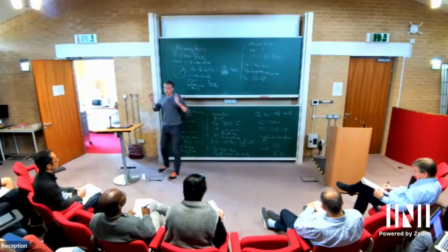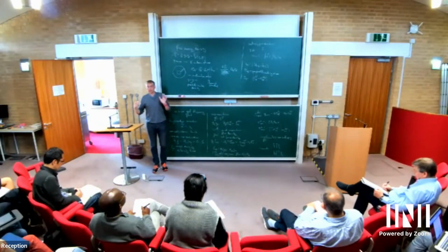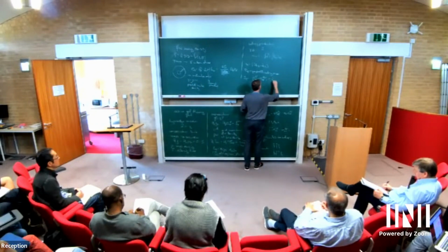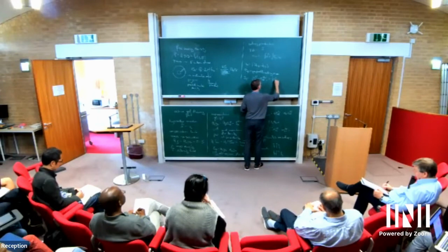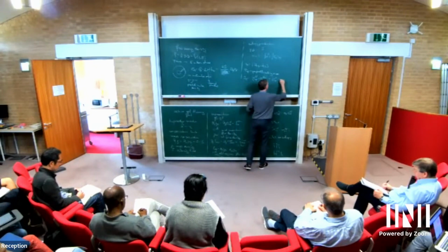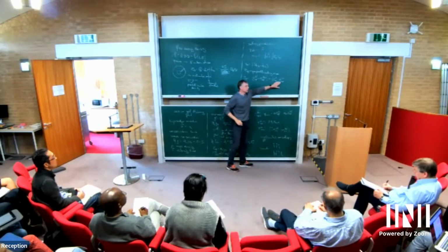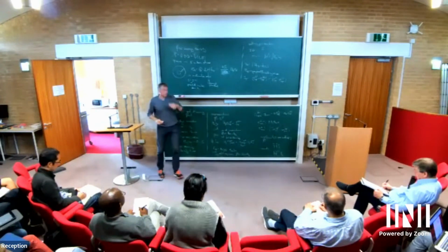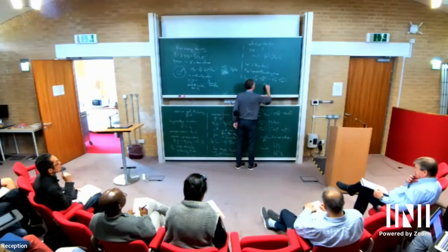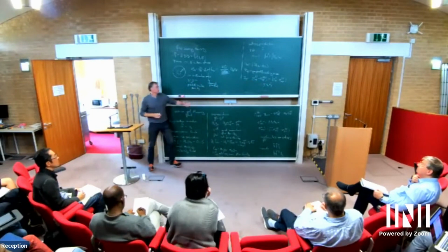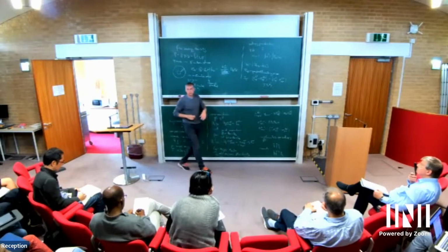And from this now symmetric part of the total stress, there are two things I have to subtract. One is the Ericksen stress, and also on this one only the symmetric part. I subtract from the Ericksen stress its antisymmetric part, and then I also have to subtract the Rayleigh stress, which is just rho and the alpha. This is already a symmetric part, so there's no interpretation necessary here.